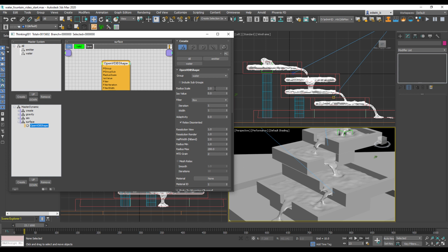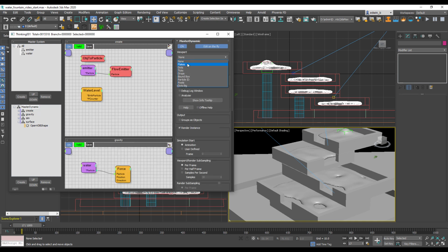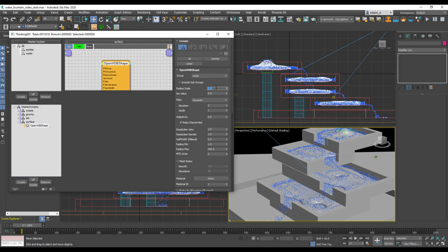We don't want these broken up or rough surfaces, so we are going to apply smoothing over the surface. We do that with the Gaussian smoothing, and then we see how that looks. We have now a much smoother surface, but now we have gaps in our surface. Particles seem not to be connecting. Let me turn on the particles, and we see there's a lot of particles without surface. We don't want that. So how can we counteract that?